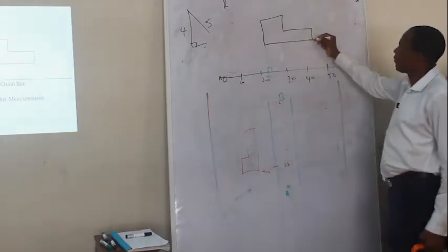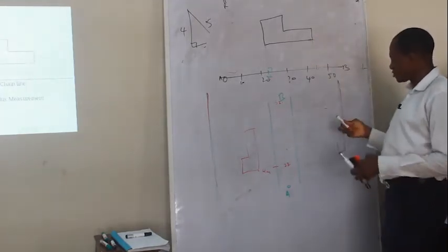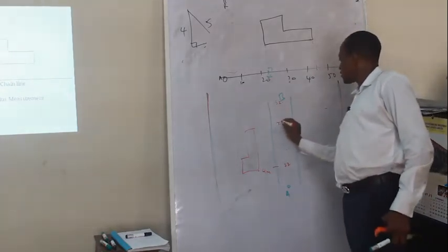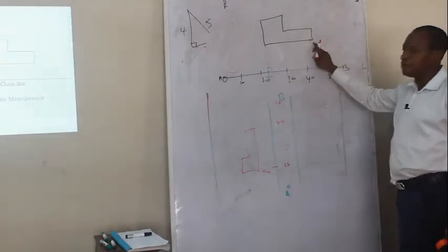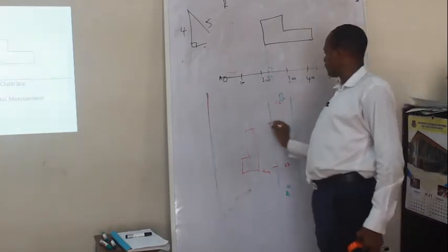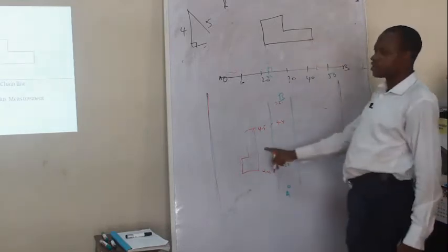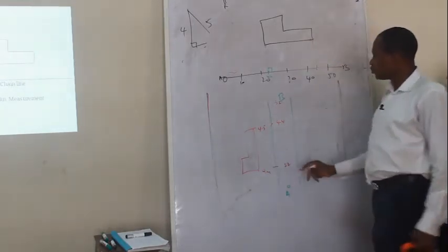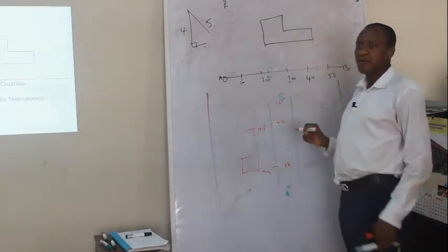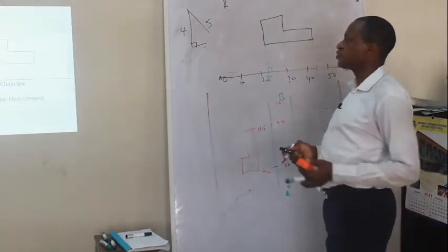As I go on, when I reach this place again at, let's say, 44, I will say at 44 I saw the end of the building. The end of the building at 44 is this. So what is the distance from here to here? Oh, it's 4.5. I say, okay, from here to here is 4.5. So you note it in your field book like that. And when you fix your details like this, and you have noted them in your field book, we call it the offset method.